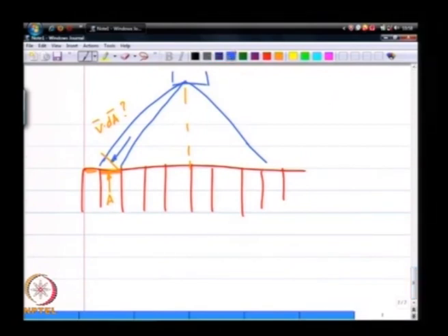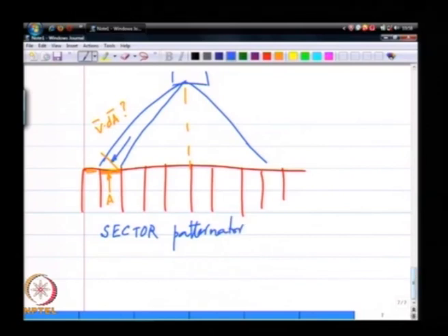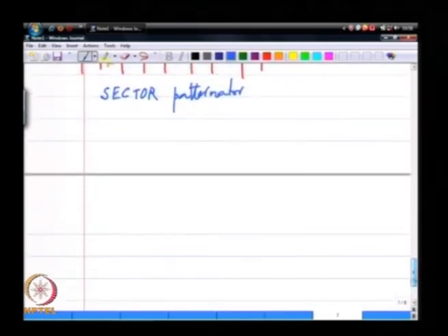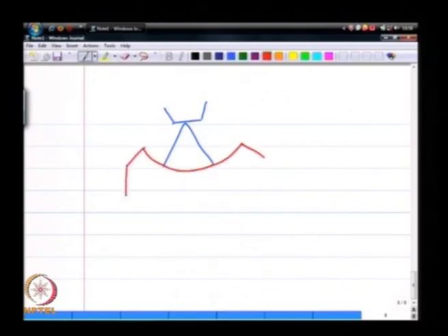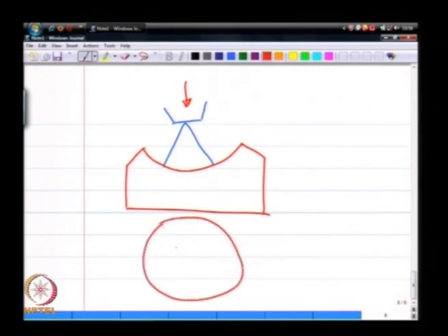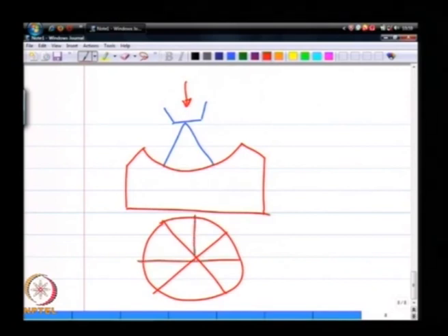is responsible for collecting volume in that sector. So, if Vi is the volume collected in the ith sector, Ai is the cross sectional area of that sector as the flow sees it, and if T is the time of collection, I can define the same Qi double prime, which is given by Vi divided by Ai T, and I expect Qi double prime over all the sectors to be the same if I have a relatively uniform spray.